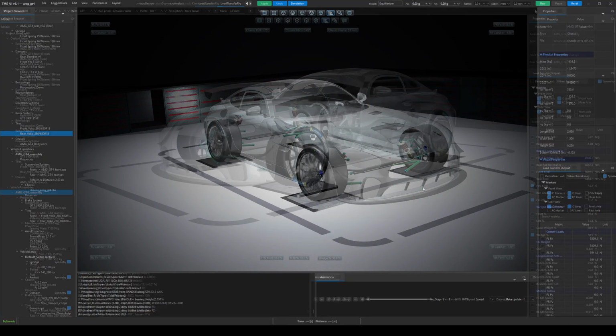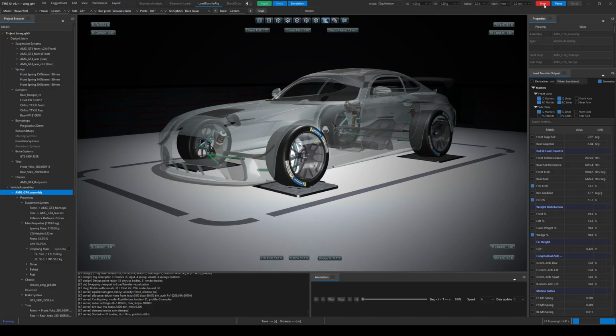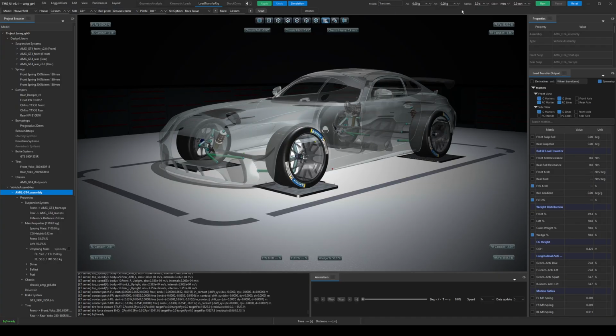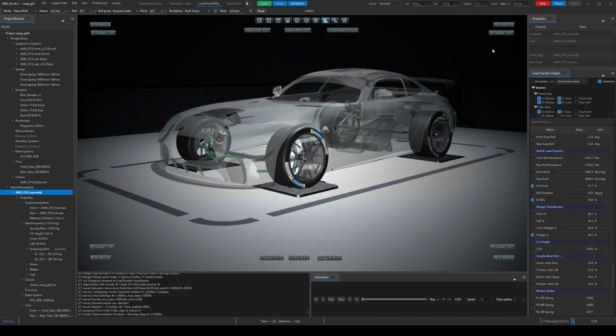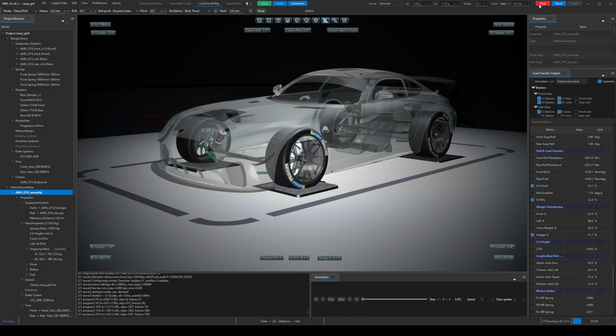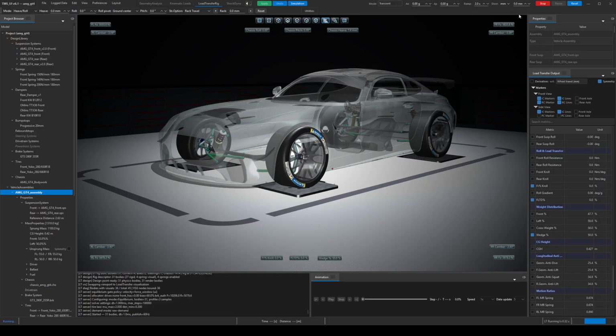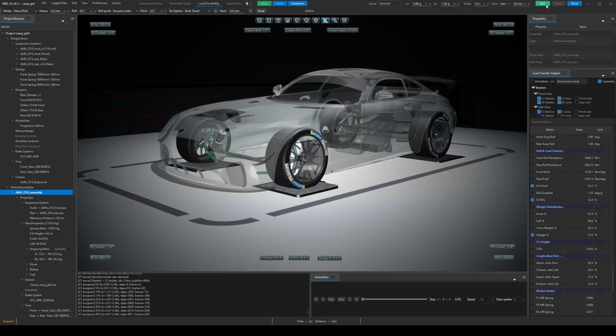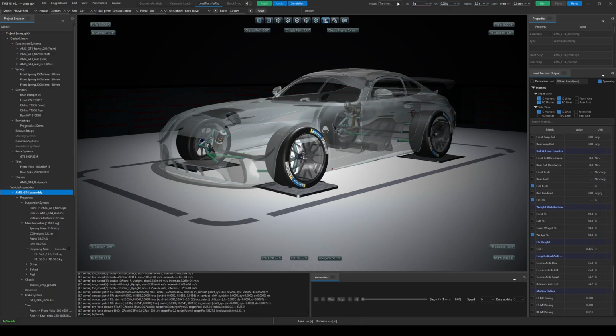For quick evaluation, there is an interactive inputs tab where the user can enter any combination of ax, ay, and steering. The user can run either equilibrium mode, which is basically a quasi-static event, or transient mode, where the acceleration ramp time can be defined. The metrics update live on the screen, so the user can immediately see how design and setup changes affect the result. It is a quick way to change a parameter, check the response, and decide whether the idea is worth a deeper look.